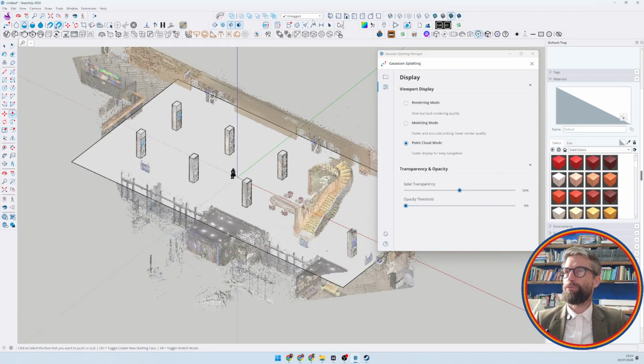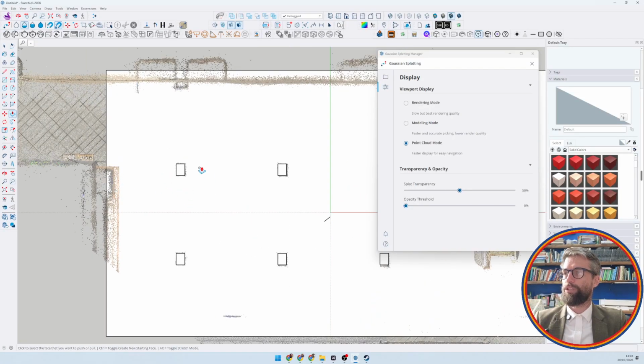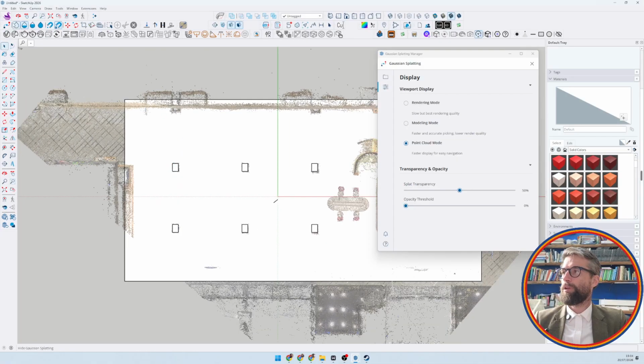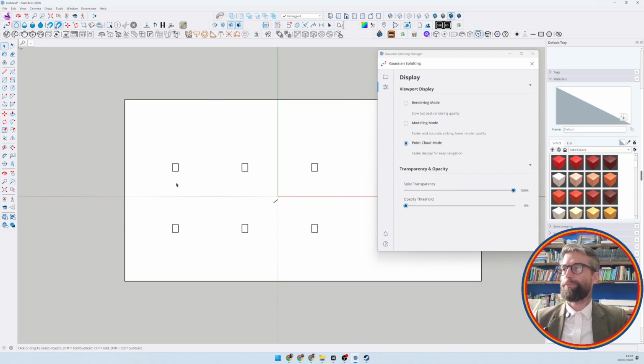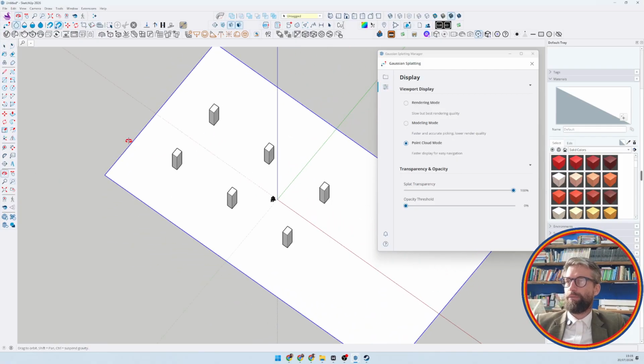So we can simply switch to an elevation view and a parallel projection to make sure that this all appears as intended. And then this is our distance between the columns. We said that was around 7.9 meters. Yeah, 7,750. And this space is 6,348. Start point to end point is 8.47. And here it's 8,500. Okay, so that's a relatively simple distance and grid that we can set out based off